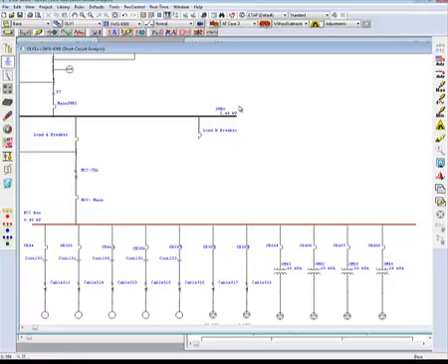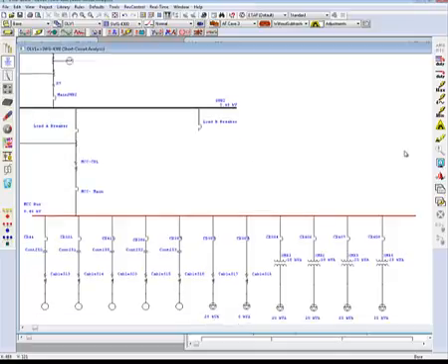Now there are certain locations that you can fault, and these correspond to an arc flash analysis. You can fault the MCC bus, or just buses, the line side of your equipment, the load side, and then finally motor terminals, or the motor terminal enclosures.